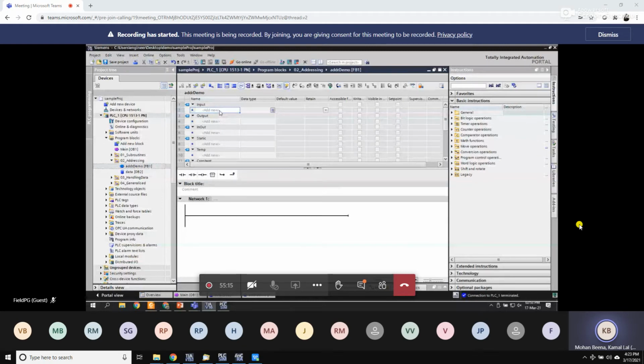One very common example I'm pretty sure all of you might have faced is when you want to create some alarm tag for HMI panels. You know that our HMI panel does not take a single Boolean bit as the alarm trigger bit, right? We have to combine it into an integer, which is actually 16 bits in size, and then take it. So that's what I want to show here. So let me make some bits. So bit 1,